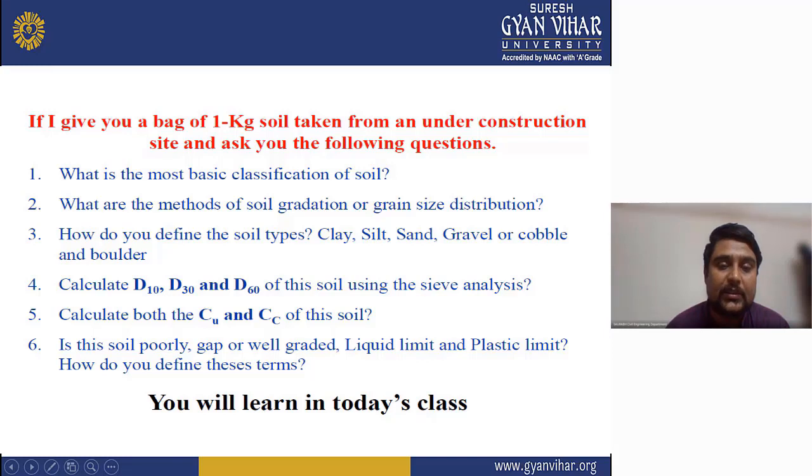What is the significance of sieve analysis? The distribution of different grain sizes affects the engineering properties of soil. Grain size analysis provides the grain size distribution, and it is required for classifying the soil. These are the major groups of soil: cohesive soil, granular soil, cohesionless soil. There are silt, clay, sand, gravel, cobbles, and boulders. These are the grain size soils.